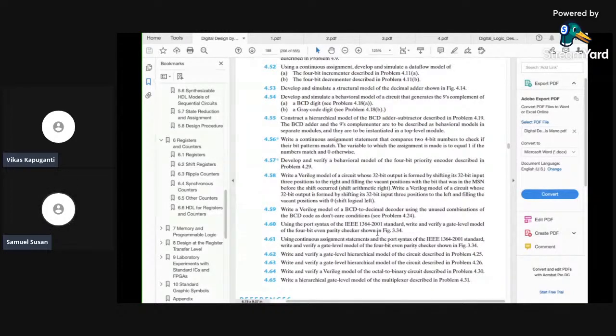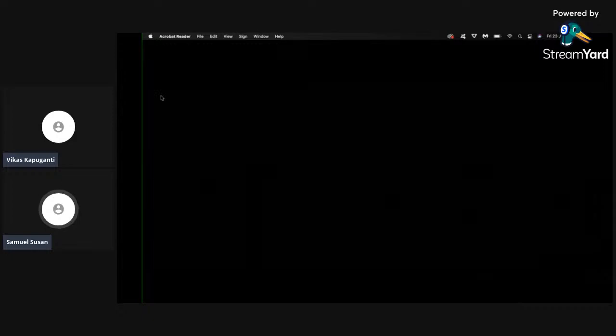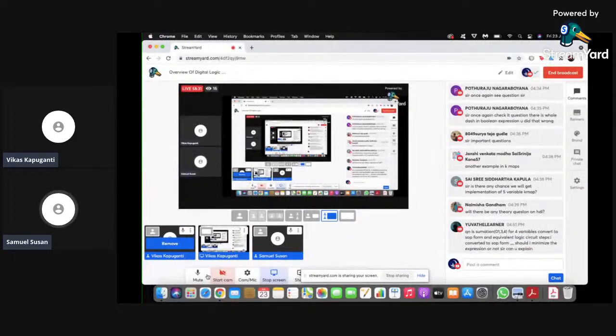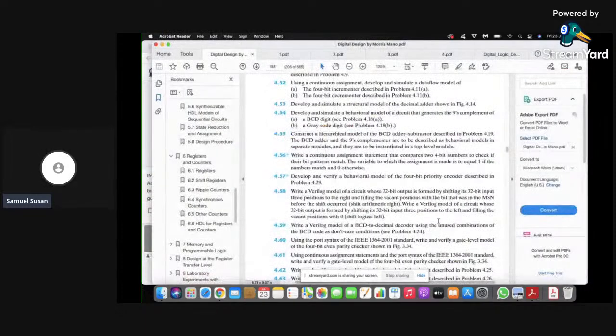Then you need to formulate a table first from the given description. Every combinational circuit generally has four properties: block diagram, truth table, equations, and circuit diagram. The block diagram shows the inputs and outputs and their names, and then we go with the table. If I can formulate the table from the given description, you can find the equation using the K-map, and finally after the equation you can give the circuit diagram. That is the general method you follow in designing a combinational circuit.